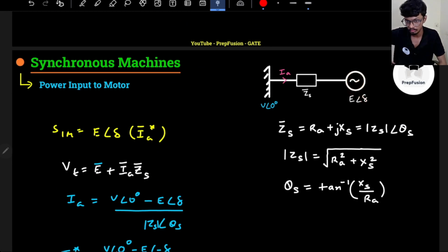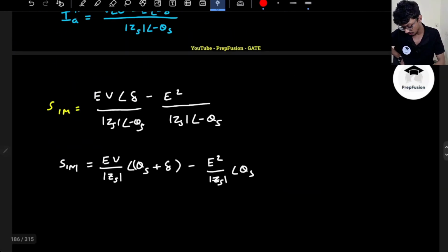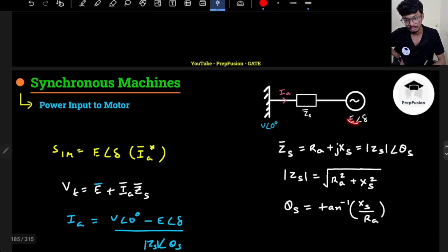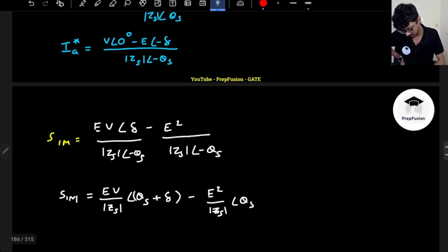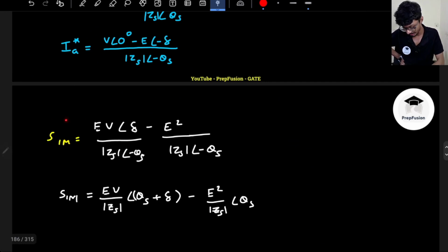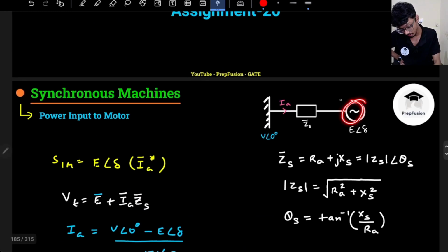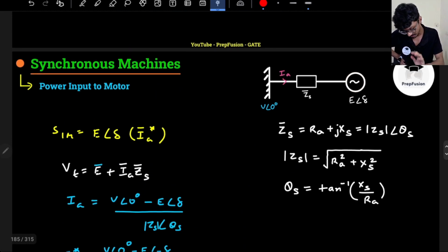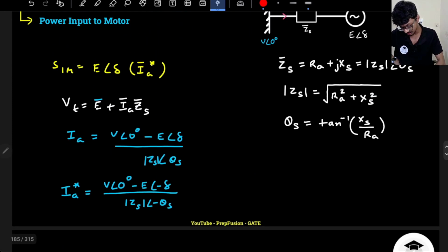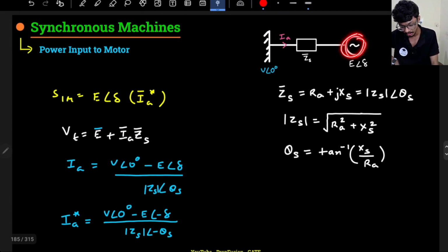Now you might have a doubt, sir: how am I getting apparent power output of the motor if the motor can drive an active load? Of course, the motor needs reactive power for generation of flux. So the reactive, or imaginary, component of this apparent power is the component required for supplying the reactive power. I will explain.